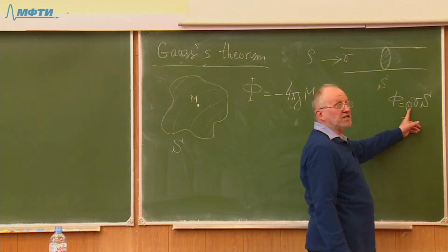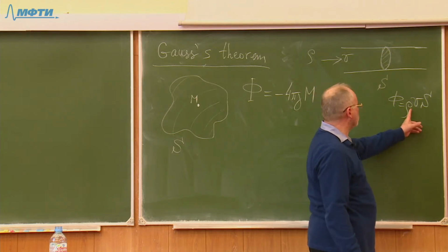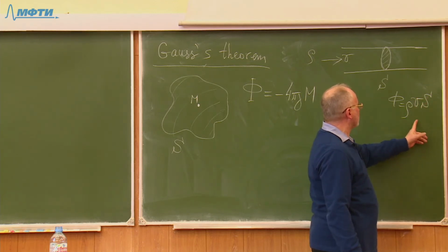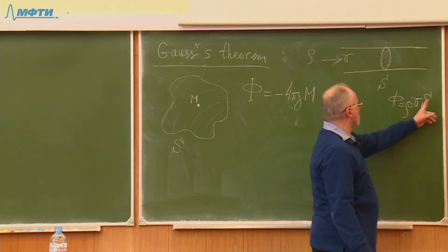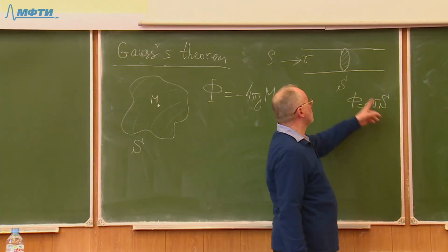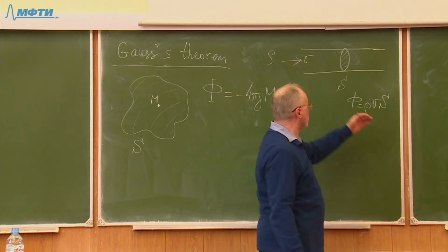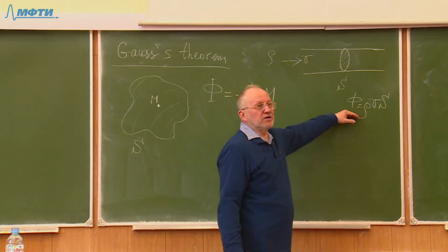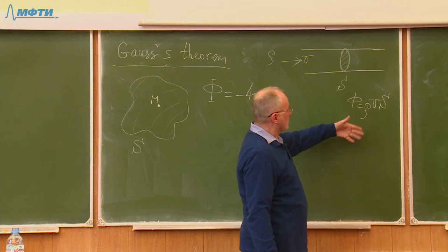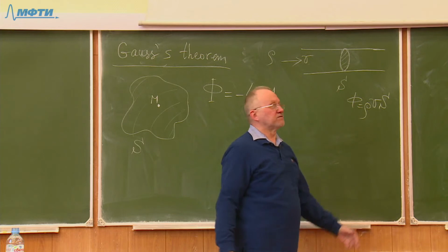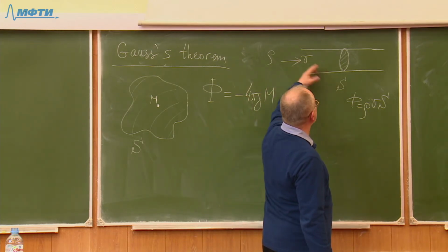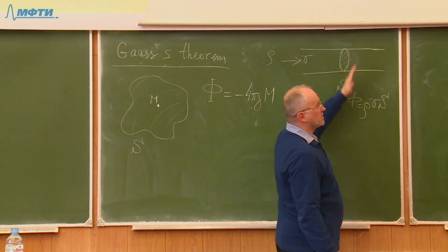the density is kilograms per meter cube, and here you will have meter cube per second. So meters cube will cancel, and you will have how many kilograms per second flow through this tube. That's the physical meaning of such a quantity as flux. It's simple when you consider the flow of liquid. The flux is how many kilograms per unit time flow through the cross-section of this pipe.